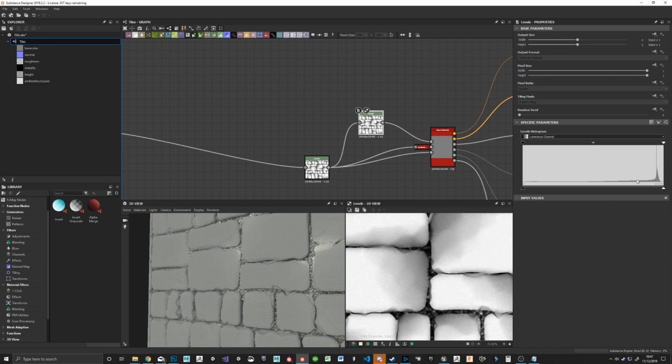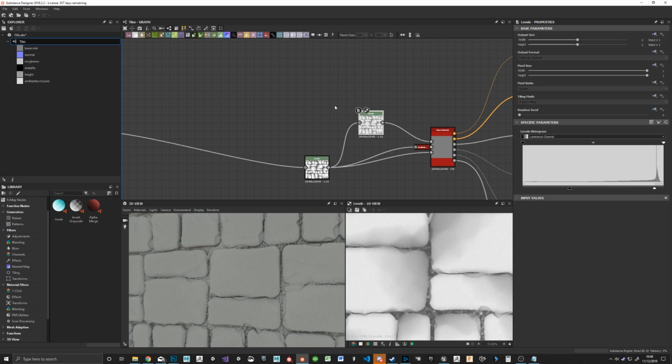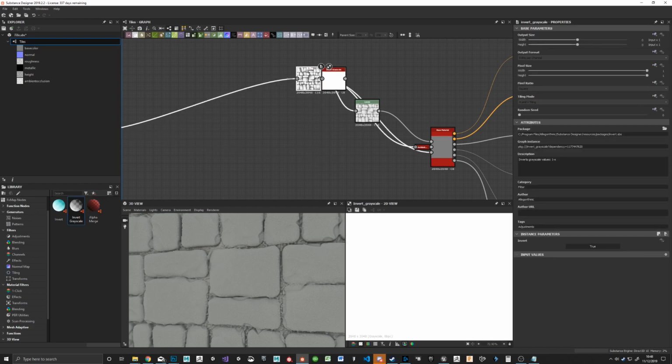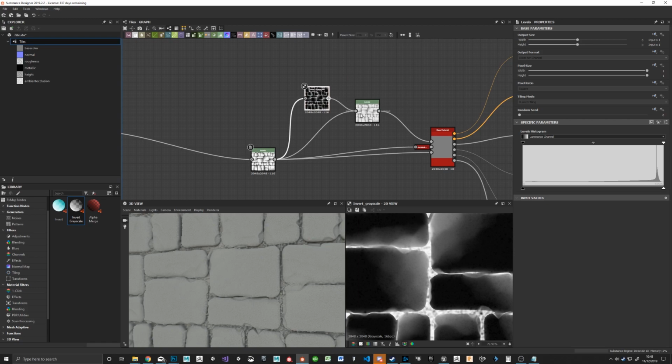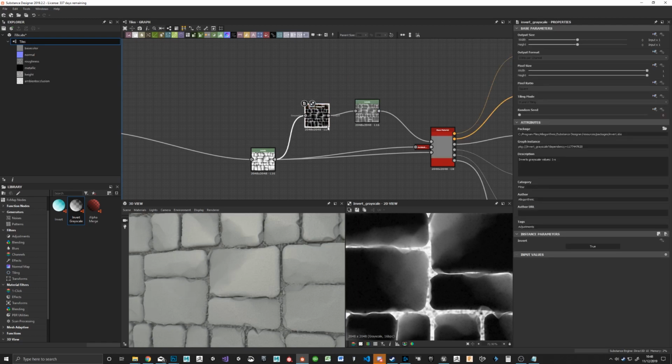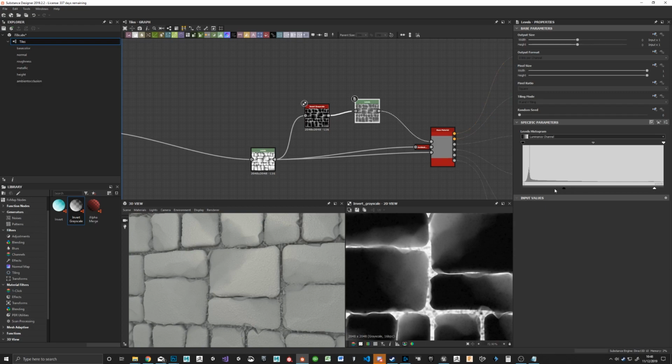What we can do from here is pull down that white. I should pull it down from this direction and take away that black, because we're not using metallic or anything that's smooth on this particular thing. We could probably even invert it. That might be a good one. So you can use an invert grayscale. That way we know that our top surface is going to be a little bit more smooth than our bottom. And then we can go in there and adjust those levels.